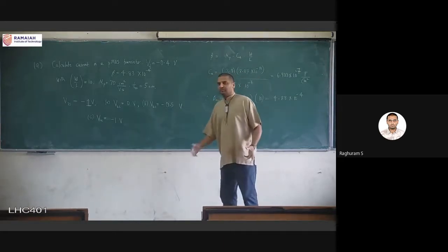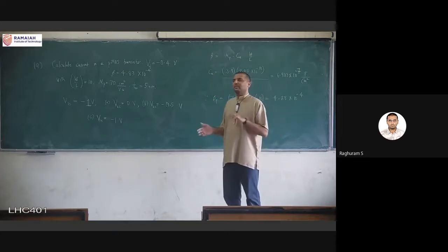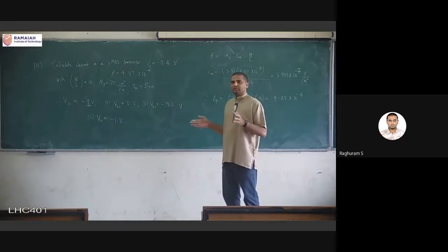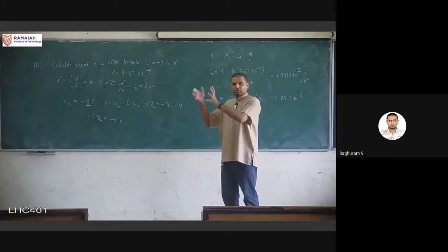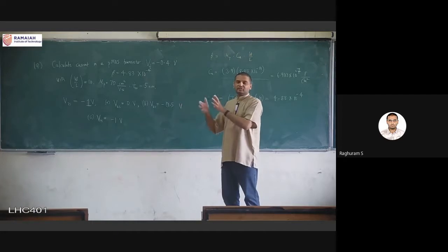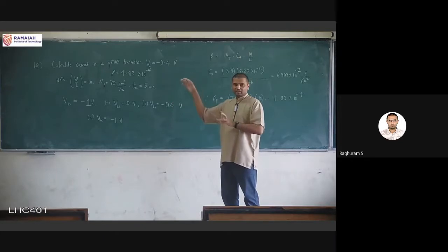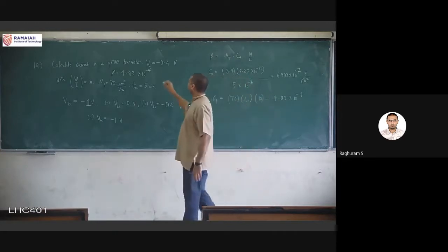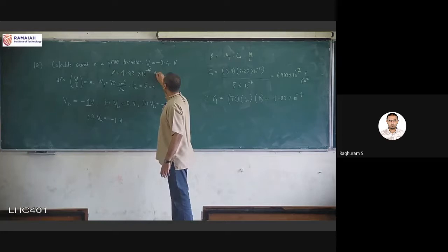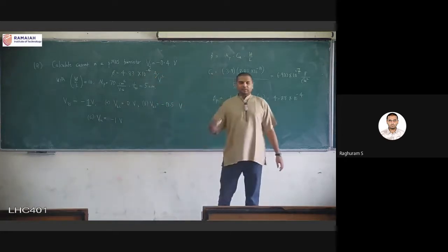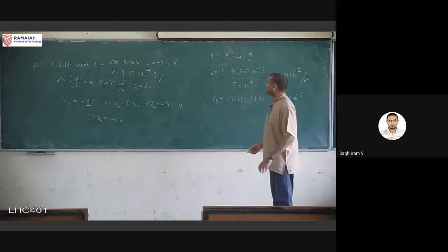It is difficult to imagine what the units are directly, but indirectly, if you see the current equation, it is I equal to beta into voltage into voltage, that is VGS minus VT minus VDS into VDS, or VGS minus VT the whole square. That is beta. If you do the dimension analysis, if you cross multiply, it should be ampere per volt square, so that it will get cancelled and you will get ampere. So that is our beta.